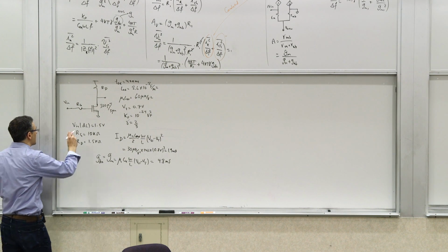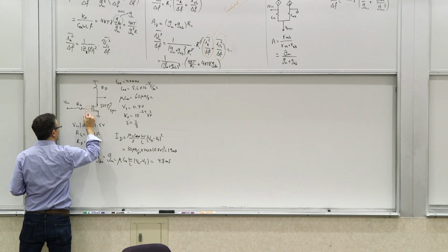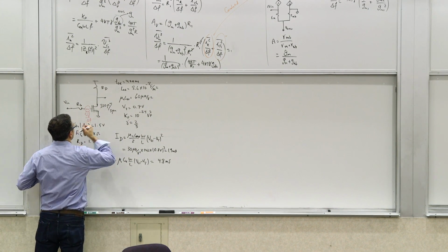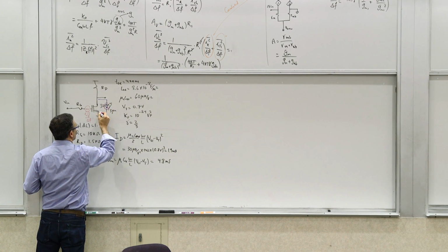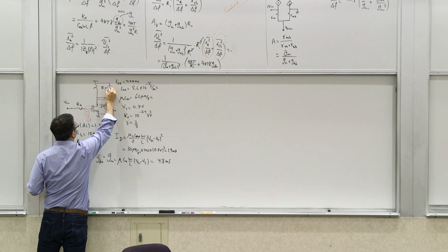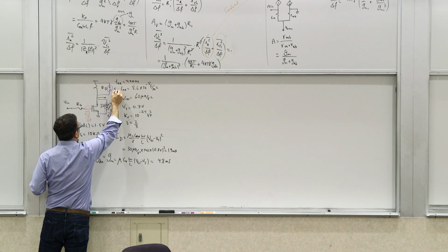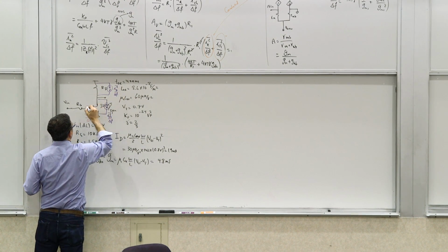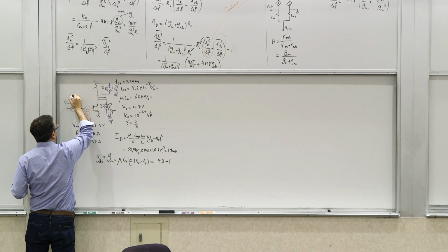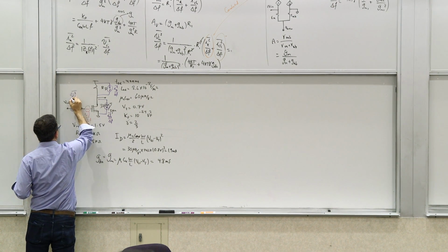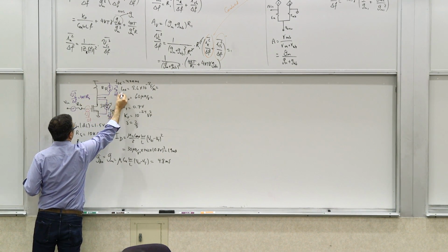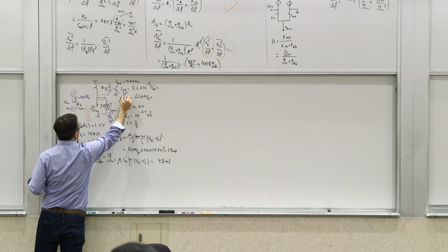There is the flicker noise of the transistor, which is sitting here, right? There is the channel thermal noise, I channel squared over delta F. There is a noise of the output resistor, I d squared over delta F. And then there's the thermal noise of this gate resistor, which is Vg squared over delta F. So this is obviously 4kT Rg, and this is 4kT over Rd.